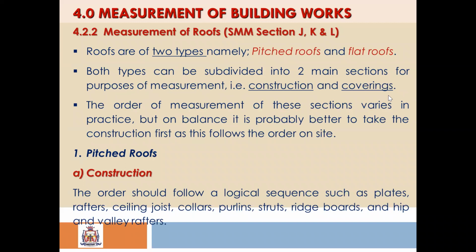But meanwhile, let's go with the notes. So I said you consider, first of all, you look at the plates. Then we assume that after the plates, the wall plates have come on. The wall plates are normally the timber that is laid across the wall. These support the trusses, the roof truss. That's what we call the wall plate.